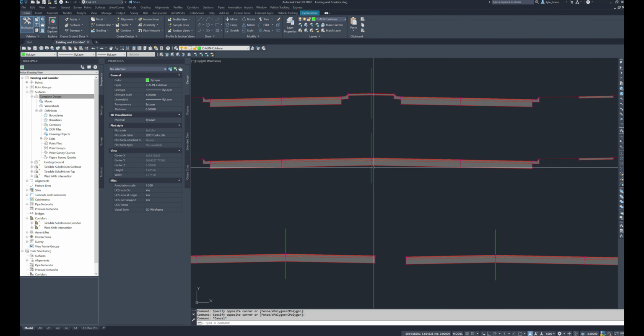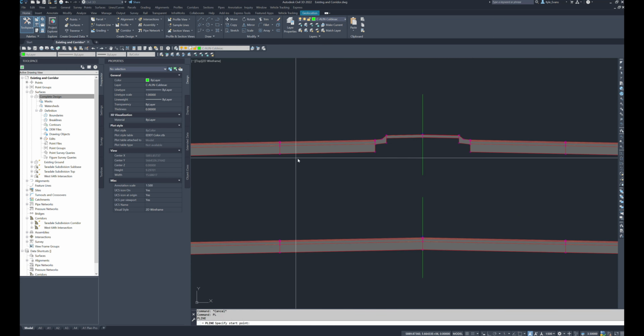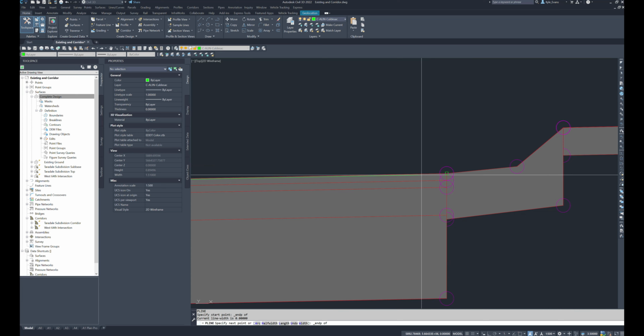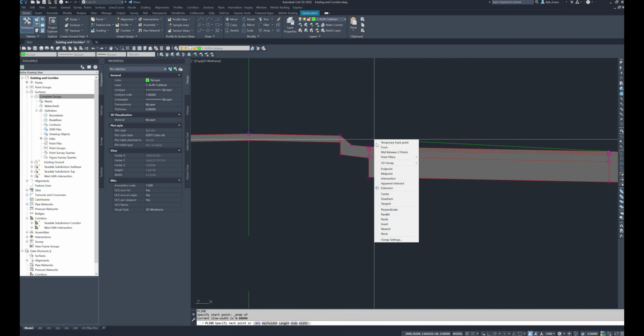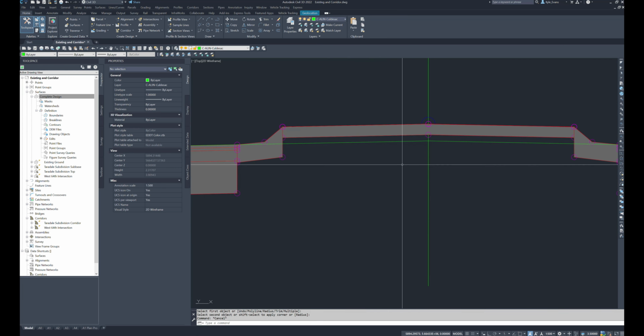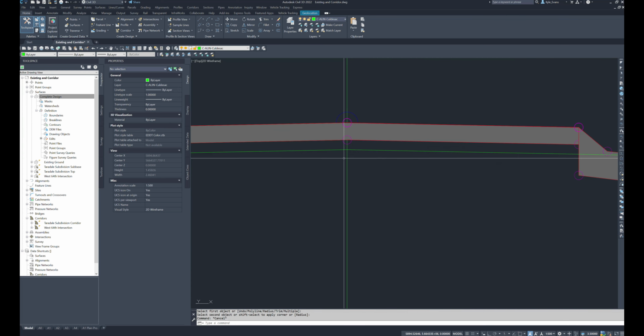Now these are going to be two very different elevations, and the easiest way that I've been able to figure it out is with a polyline. We can draw a polyline from there to there, and I'm going to draw a polyline from there to there as well. And I'm going to fillet those together with just a radius of 0 to find out where that theoretical high point would be on our assembly. So if these lanes were to continue up, this is where the elevation would be.